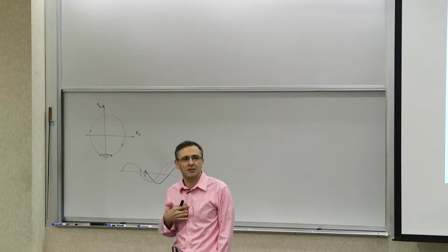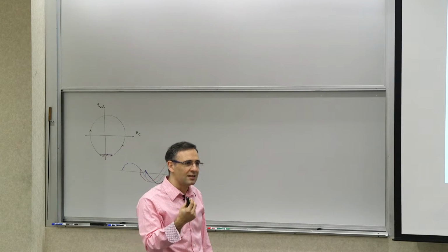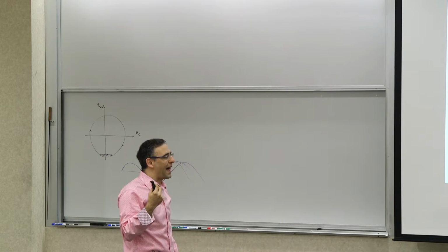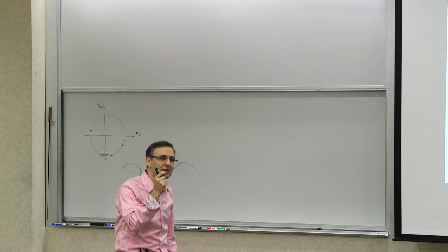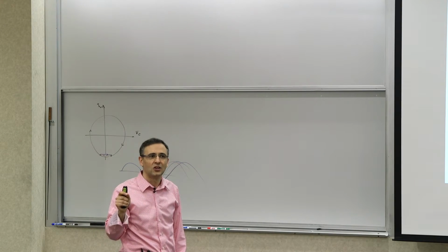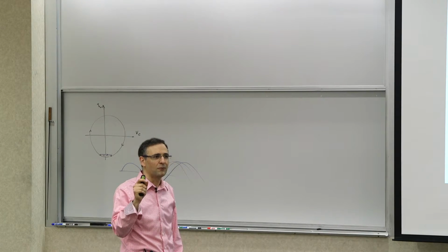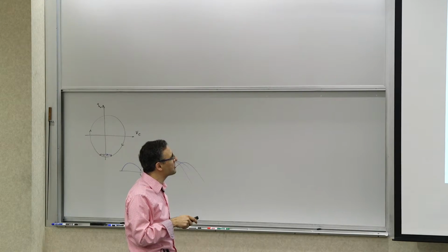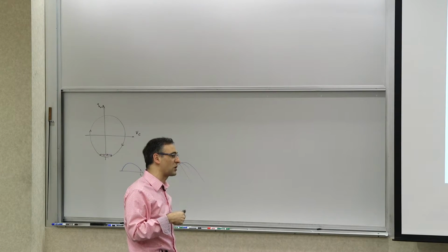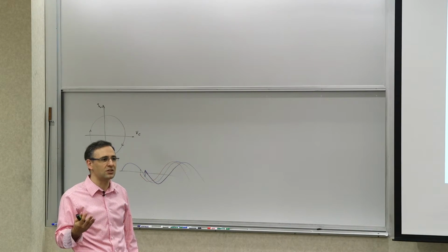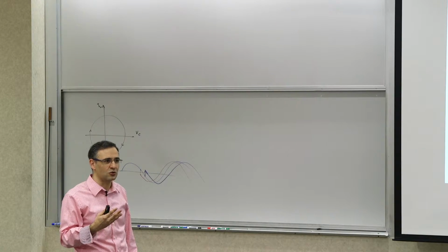It's not a proportionality constant, it's a proportionality function that changes with time, and it's a measure of how sensitive each point in the waveform is to a perturbation of phase, right? How much phase you get from a perturbation. We call this function the impulse sensitivity function, because it captures the sensitivity of the oscillator to an impulse.